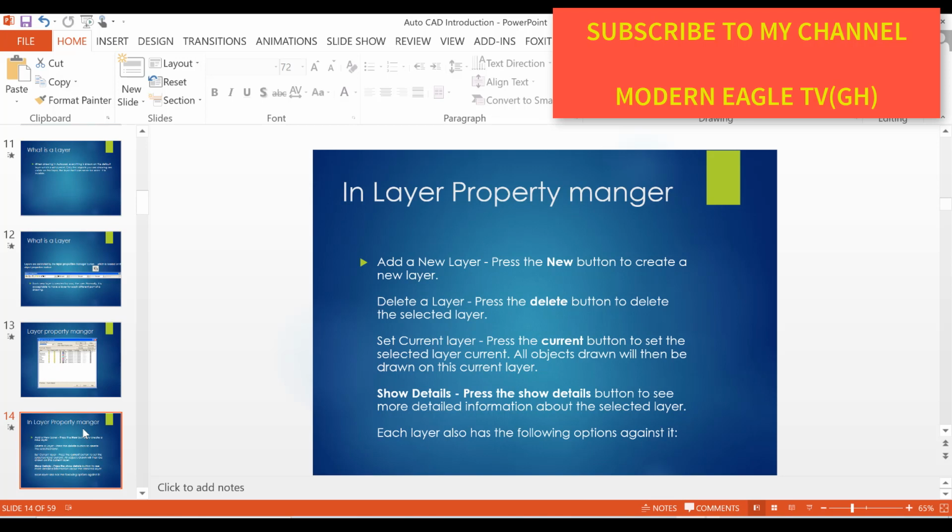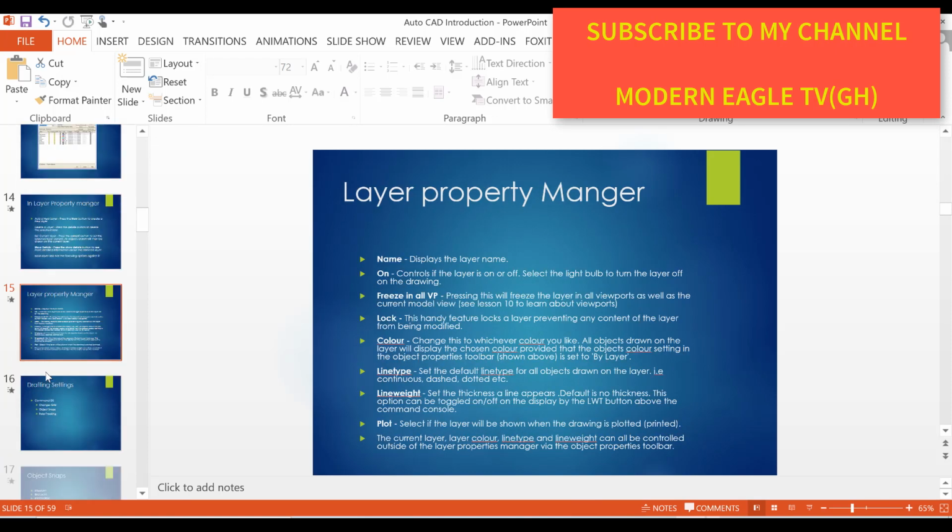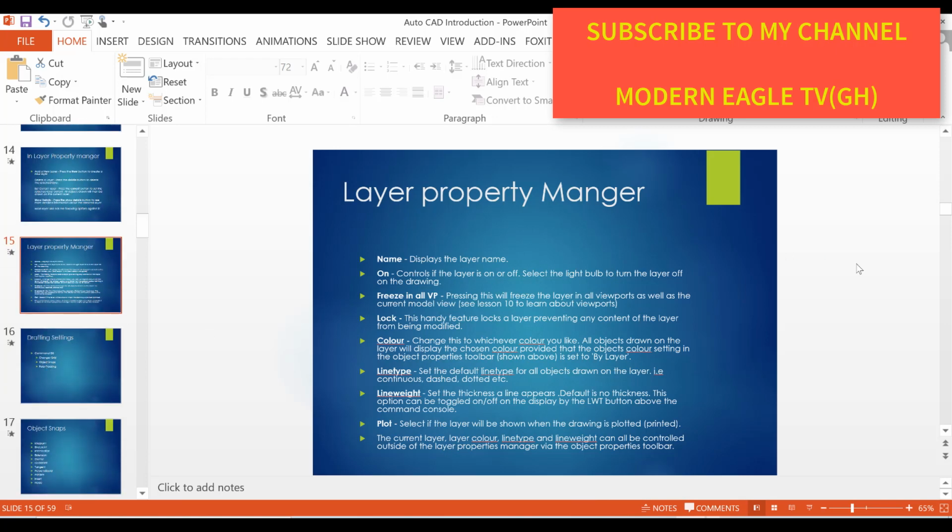Each layer also has the following options against it. Name: displays the layer name. On: controls if the layer is on or off. Select the light bulb to turn the layer off on the drawing. Freeze in all VP: pressing this will freeze the layer in all viewports, as well as the current model view. See lesson 10 to learn about viewports.